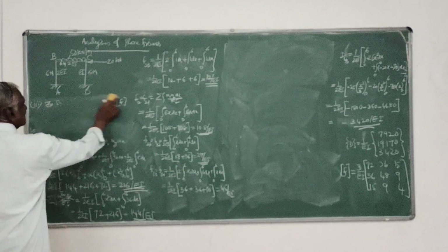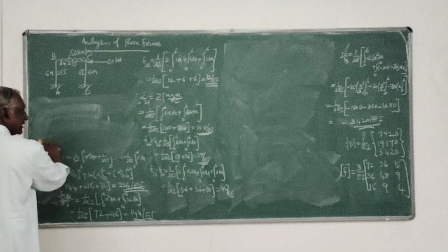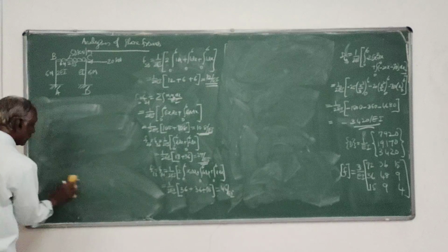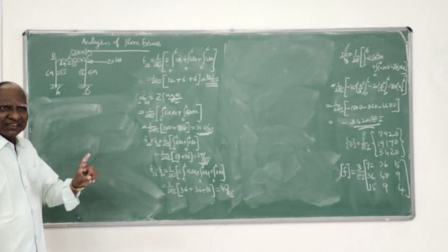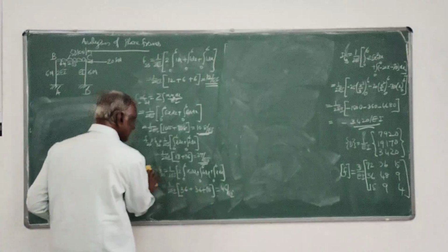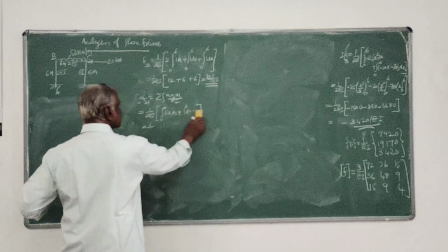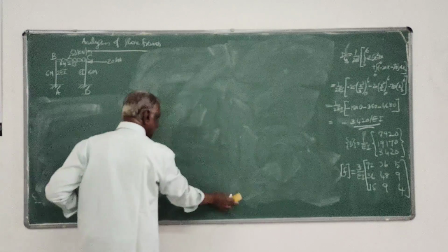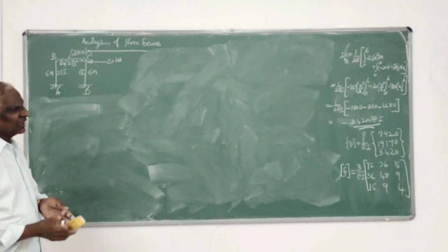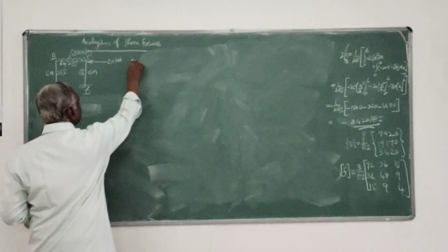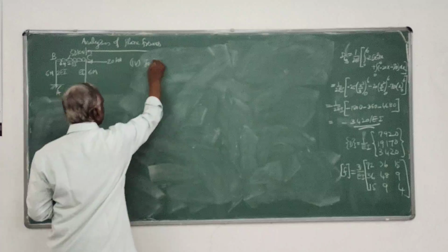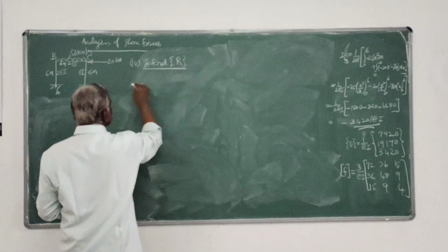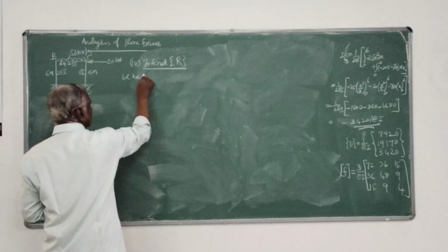flexibility matrix. This much exercise, which is nothing but largely integration and your dummy load method of preparing things, you should have the prerequisite of previous class courses, that is applied mechanics, all those things. Your strain energy method, you have to remember. Then the last step, the fourth step, is to find the redundant forces. So you use the force displacement relationship.